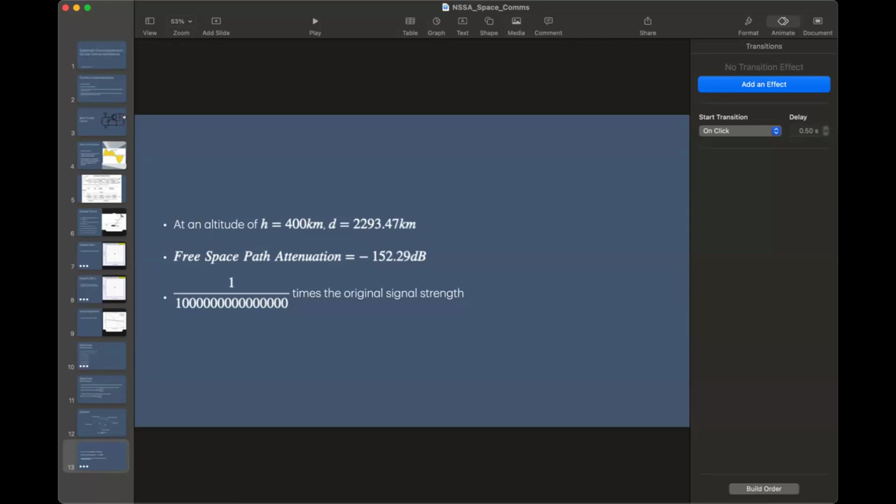We go through a series of resamplings, a filter, then we receive it in FM, then we resample the audio signal, and then we transmit it again to the wideband transmit, resample it again upwards, so we upsample it, having downsampled it before, and we send it to another connection which connects to this again, but now to the output, to the transmit side. Okay, so keep your fingers crossed.